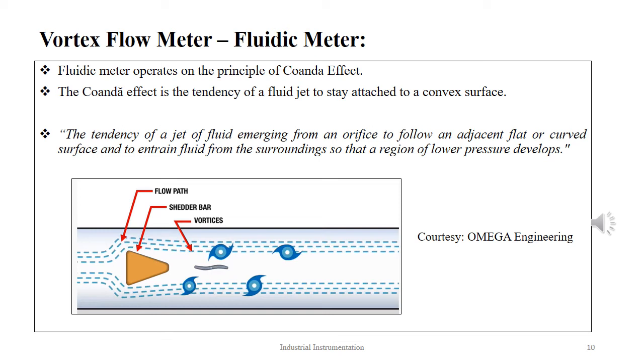The jet can be made to oscillate in two ways. In the first method, two ports are connected together and the fluid is sucked from the high pressure side to the low pressure side, causing the jet to switch to the other wall. The jet thus continues to oscillate as the fluid is sucked alternately from one side to the other.